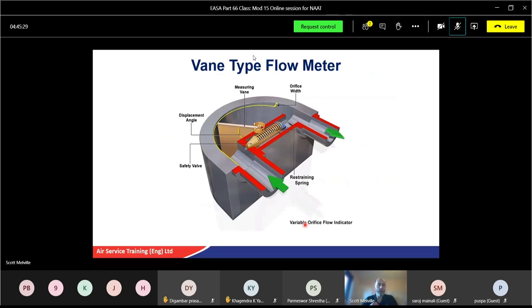The one we saw earlier on, which looks like a boat and a rudder. This is the vane type flow meter. Again, it's freely pivoted. So with this rudder type system in the back here, the fuel comes in, it will push against this measuring vane, and as you can see, there's a tiny gap that does get slightly bigger as it goes round, and it's a calibrated gap.